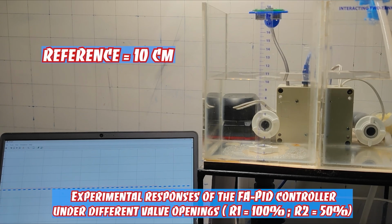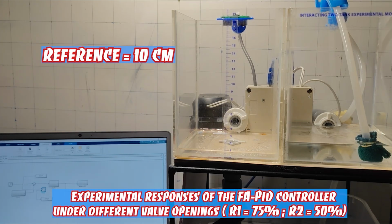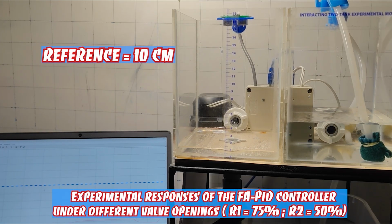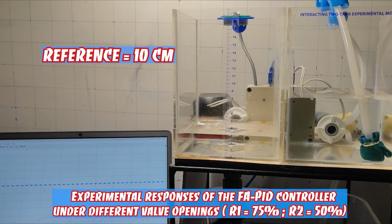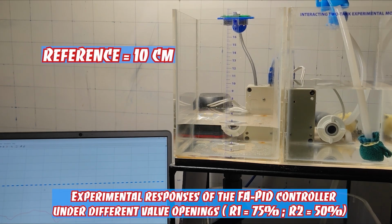This also causes the nonlinear disturbance of the system to increase significantly, but it can be seen that the response signal still tracks the reference signal quite well. In the next experiment, I reduce the valve opening by 25%, meaning that valve R1 is now open at 75% and valve R2 at 50%.